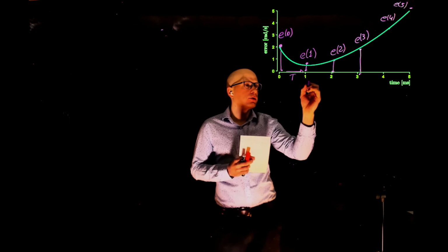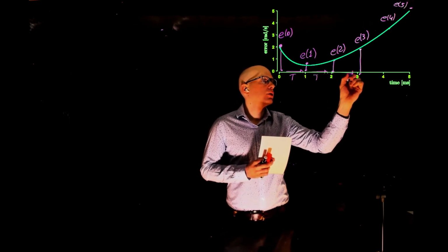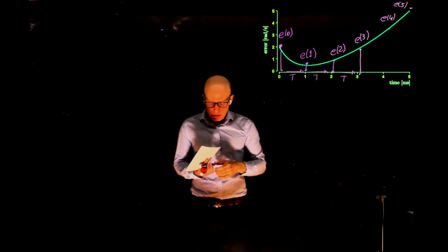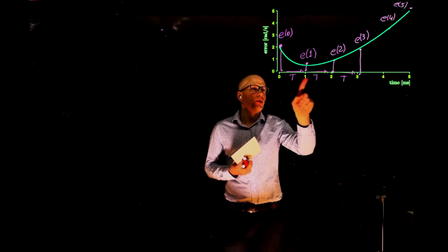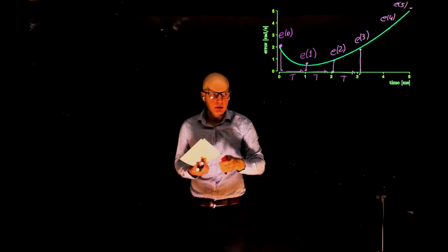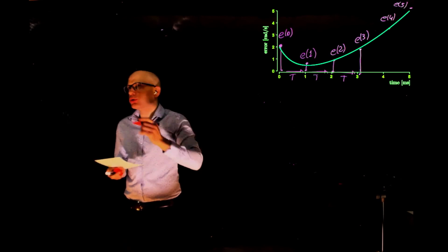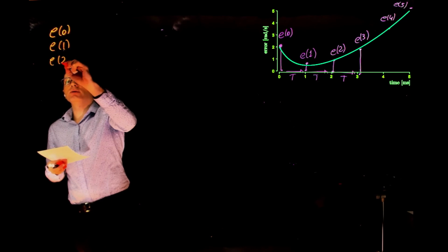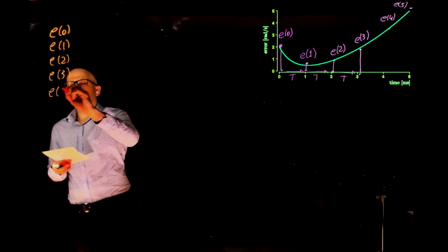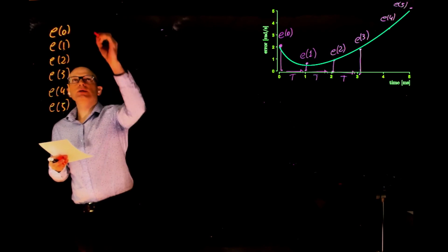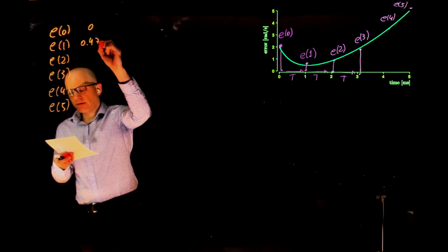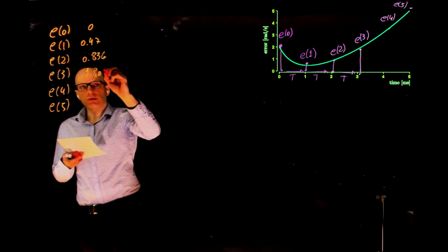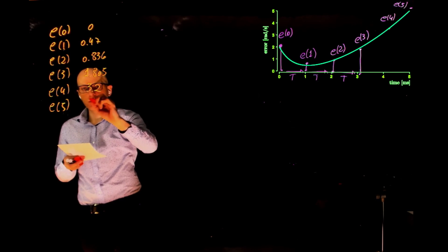I sampled at intervals that you see here that are regular and are called t. So these samples that we observed, we can just plug these numbers, 0, 1 millisecond, 2 milliseconds, 3 milliseconds, into the curve just to simulate what the microcontroller would see. And that would give us the following values that I'm just going to give here: 0, 0.47, 0.836, 1.805, 3.2, and 5.